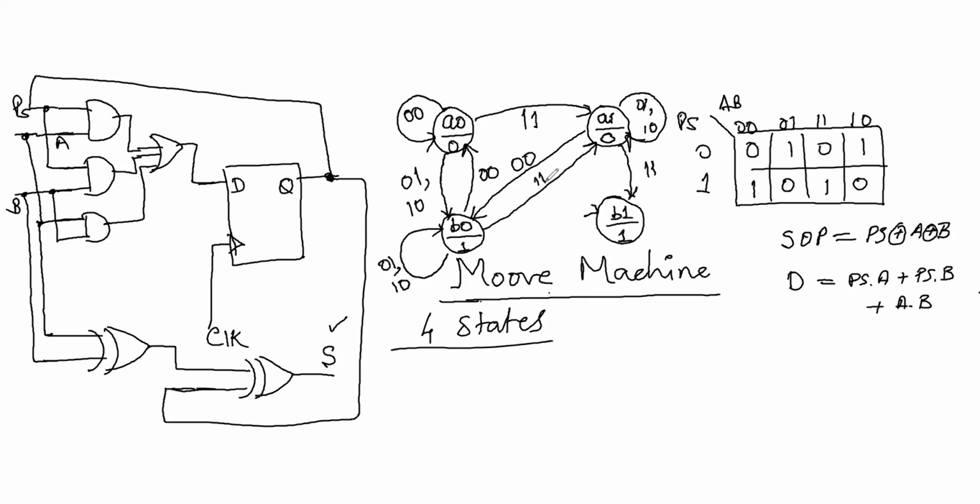Okay, now only this state is left out when your partial carry is 1. So when your partial carry is 1 and you get a 0, 0, that means there was a 1 added to it. So output should be 1, but carry should not be 1. Okay, output is 1, but carry is not 1. So carry is not 1 means the partial carry out becomes 0. So this is this state for 0, 0.